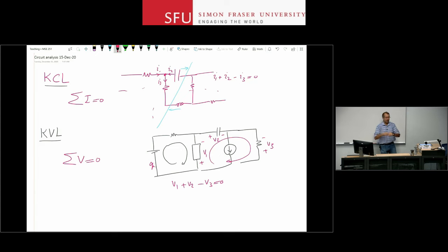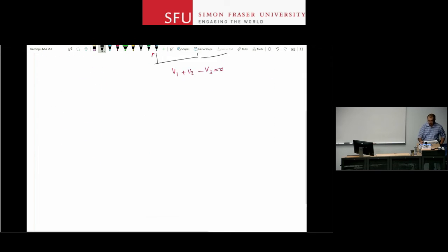You start from that level of energy, go around the loop, come back to here, you should have the same amount of energy. And therefore Q times all those voltages as you go around this loop and come back to the original position is 0. Q is a constant, an arbitrary value, so the sum of those voltages should be 0, right? So now let's go quickly through an example. I will have more detailed examples during our live sessions if there is interest from you.